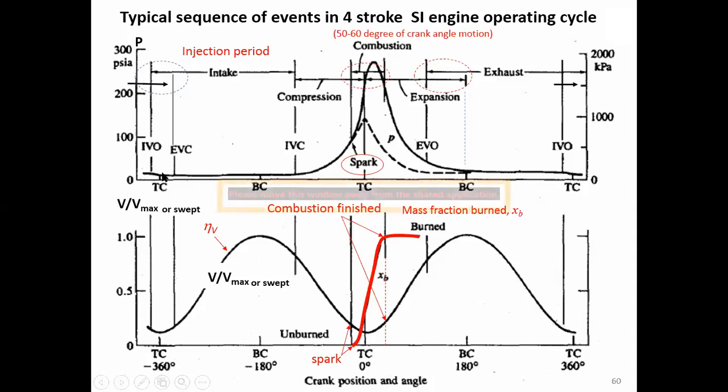Intake stroke here. So the intake stroke happens along the way that the piston keeps moving down, while the inlet valve is open and the exhaust valve is closed. Right. The intake stroke happens until the piston moves down to the bottom dead center. After that, the piston starts moving up. The intake valve is still open, not finished.